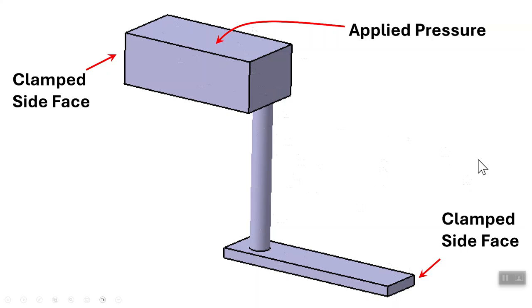Well, we don't know these things, so a quick and dirty way of estimating in a very conservative way is to say, okay, let's say that all the parts were tied together. And of course, if that is the case, you can create an analysis connection between the appropriate faces and then make them fastened, for example. That's fine. There's nothing wrong with it.